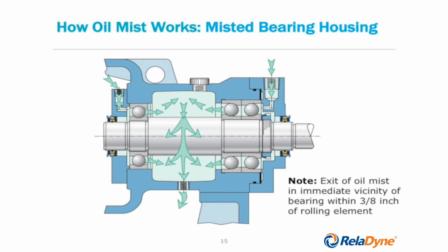The radial bearing is to the right of another one of these oil seals. And the oil mist is introduced between the oil seal and the radial bearing. After the oil mist goes through the bearing, it is going to commingle with the oil mist that already exists or has formed as a result of introducing mist from the right side bearing.